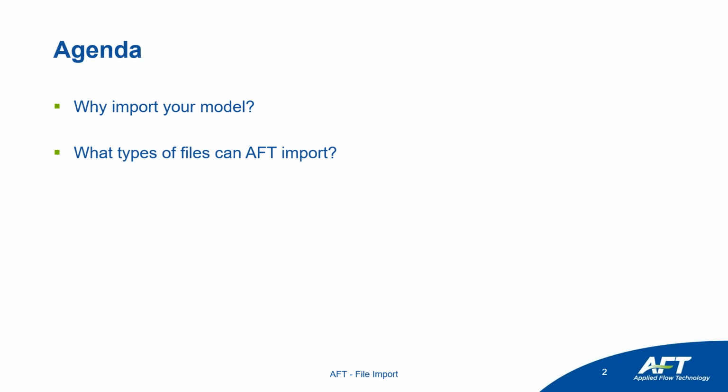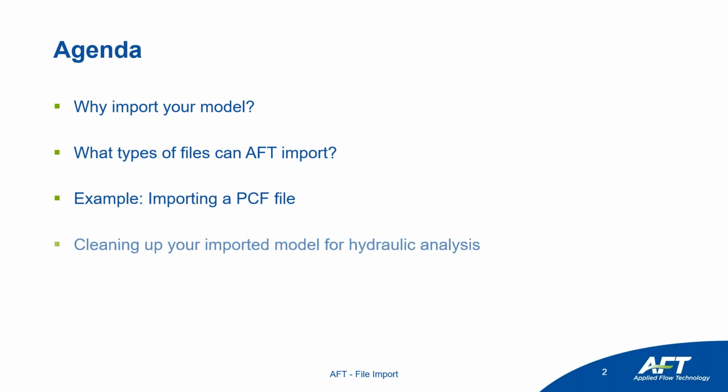So we'll look at importing from other AFT applications and then some of the file formats that you might find in CAD software or pipe stress software that we can bring in. We'll go through an example of importing a PCF file, go through the process itself, look at each of the points individually and see what each of the settings means. And then finally, how can we clean up that model in preparation for doing our hydraulic analysis.